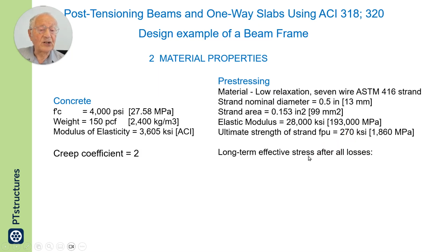And for long-term losses, as you apply the jacking force, the force in the strand will be higher than long term. With passage of time, some of the force will be lost, as well as some will be lost along the length of the tendon due to friction.